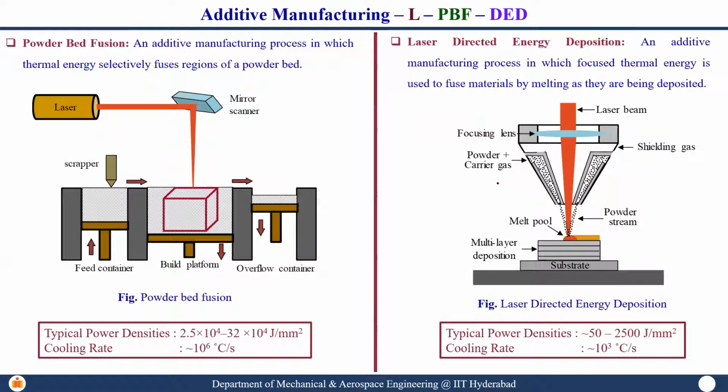In a broader way, I kept it in a very simplistic manner. This is the powder bed fusion process, and you can see there is a scanning laser. All of us know there is a build platform. It moves down by a predefined thickness or displacement, and then from the feed container the powder comes out in a metered quantity, what we call the dose factor.